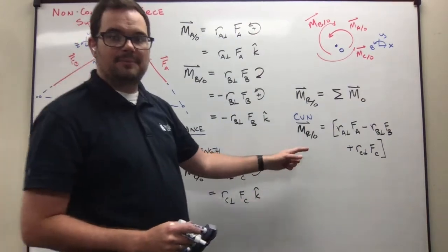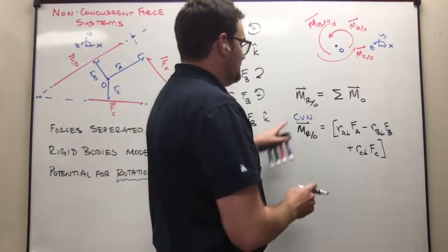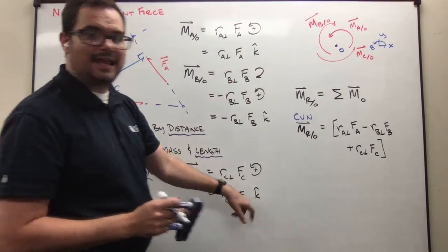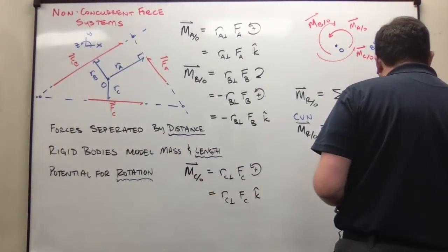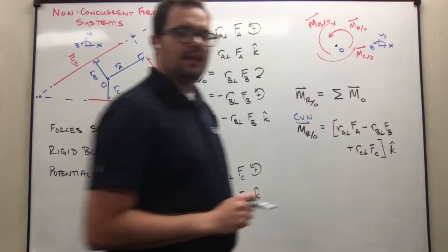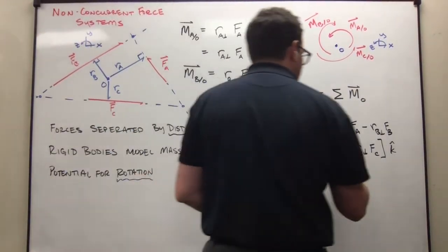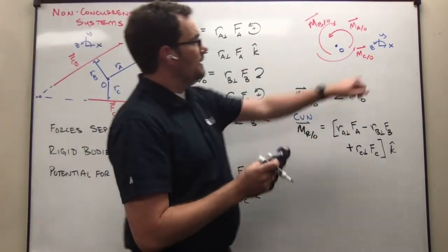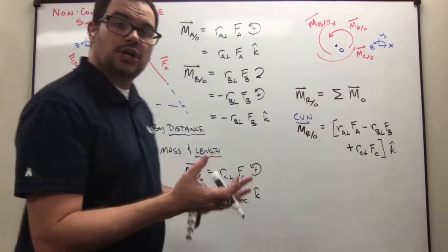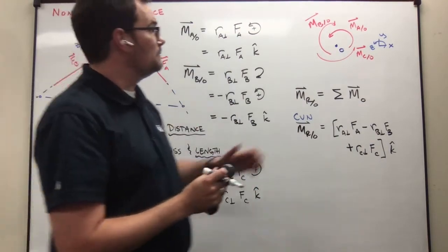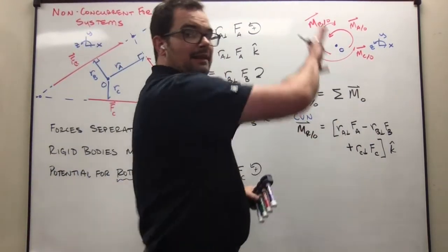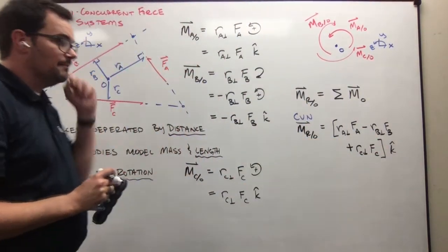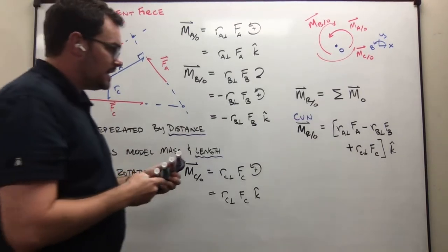So I've done some line wrapping, add up all the values, and then because it's Cartesian vector notation, I'm going to collect that K unit vector and put it out here at the end, like so. And we're keeping track of our positive and negative moment values because some of it's encouraging. So moment at C, moment at A, those are both encouraging clockwise positive rotation. And B, sorry, right-hand rule, is causing that negative rotation, resisting the other two. So this might in fact add up to 0 because yay, nothing moves.